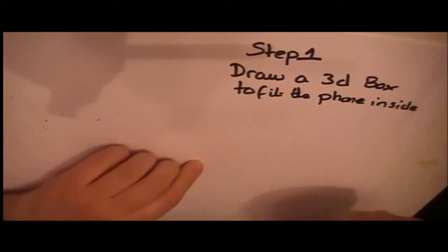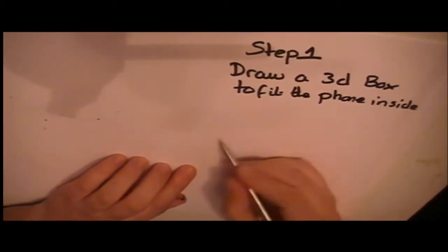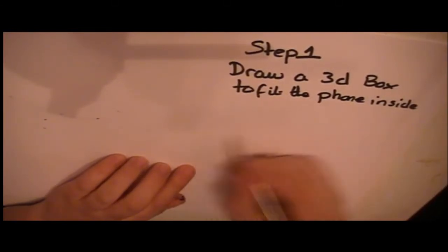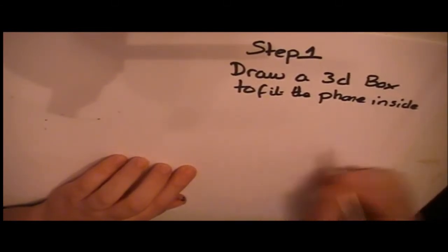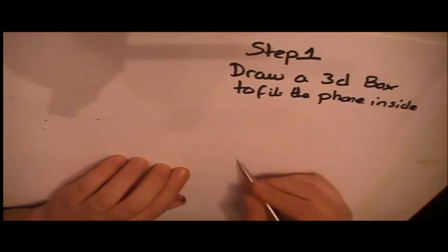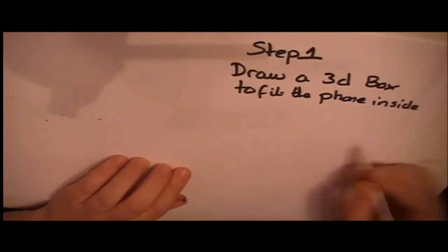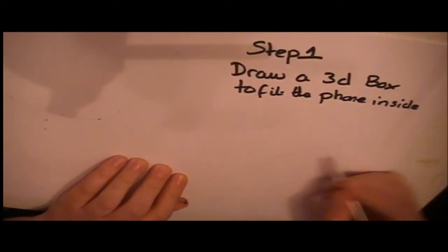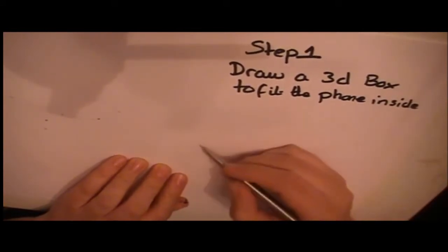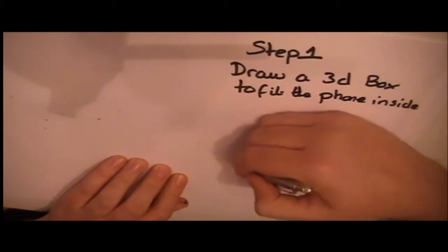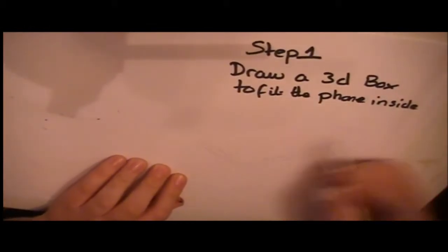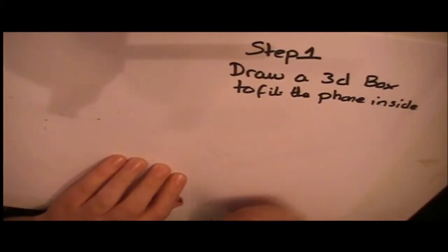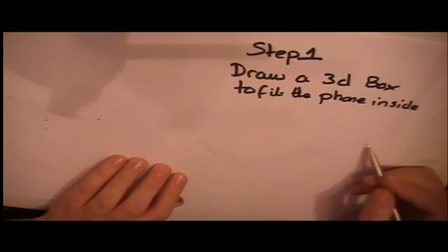So we're going to take our pencil now, and we're going to very lightly, and it is really important that you press lightly now. You don't want to press too hard when you're doing this. So we press nice and lightly, and we're just going to sketch out in isometric roughly a 3D shape. Now I'm doing it nice and thin, don't press too hard. And a little tip, if you notice my hands, it's not the correct way of drawing, make sure you turn your paper as you draw.